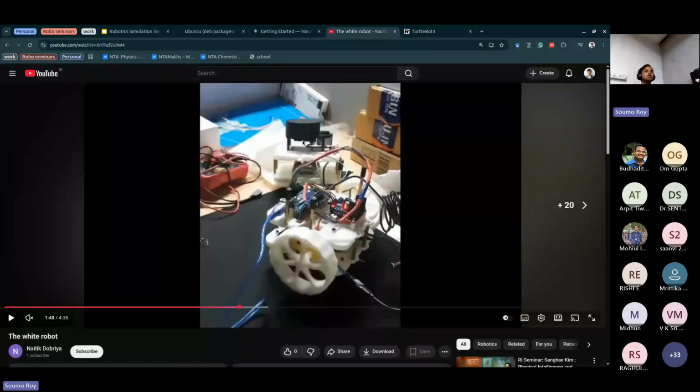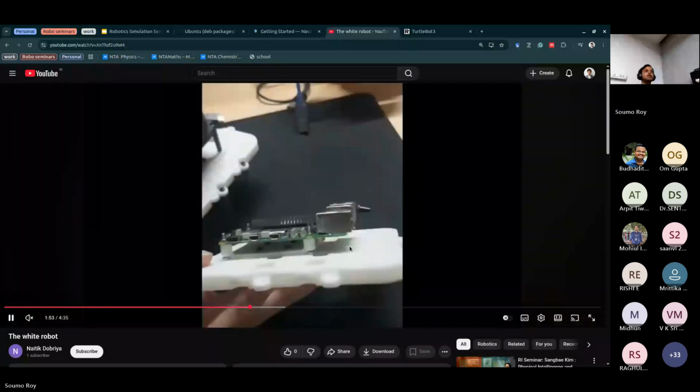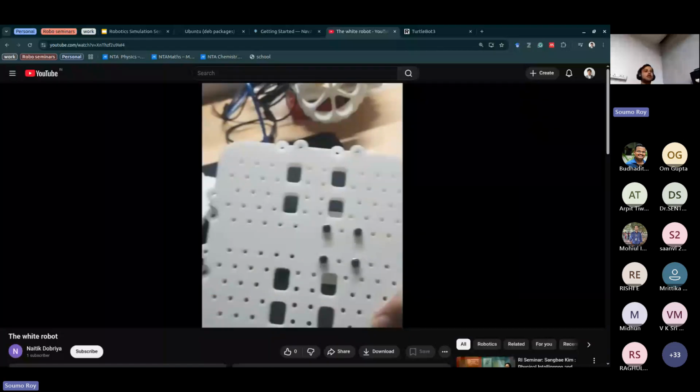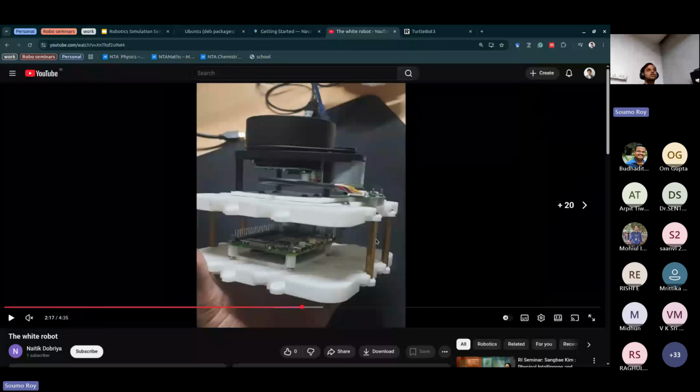So you can see a demo of these wheels spinning and the feedback given by this robot. This is a low level control board over which we want a high level control board. And this is where our Raspberry Pi comes in. Using Raspberry Pi, we are going to interface the sensor and send data. It's basically like a mini computer, like a microprocessor, where you can execute commands, so that you can send fine-grained commands using ROS, as I talked about, to interface with real-life robots.